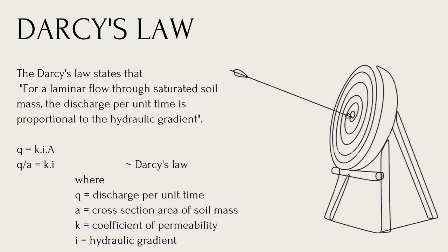There are some validations as well, which state that Darcy's law is valid only for slow and viscous flow. Fortunately, most groundwater flow cases fall in this category. Typically, any flow with a Reynolds number less than 1 is clearly laminar, and it would be valid to apply Darcy's law.